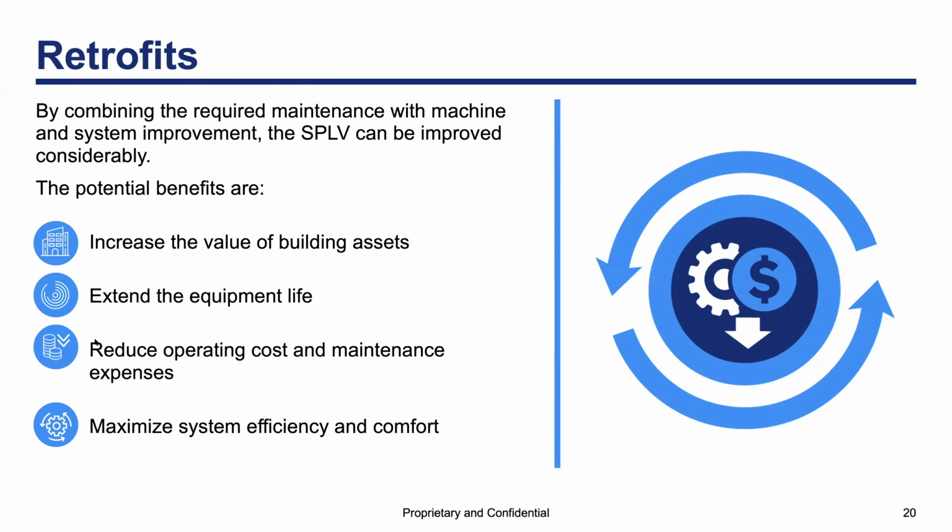And the last point to consider, remember that I mentioned three key parameters, is proper capacity control. This is more about understanding the limits of every piece of equipment. As an example, in the case of centrifugal compressors or even screw compressors, it is lift or head. Sometimes those settings for capacity control are completely off, and way off in reality. And the consequence is that we have a chiller that is not performing correctly, is wasting energy, and is causing, most of the time, temperature fluctuations.